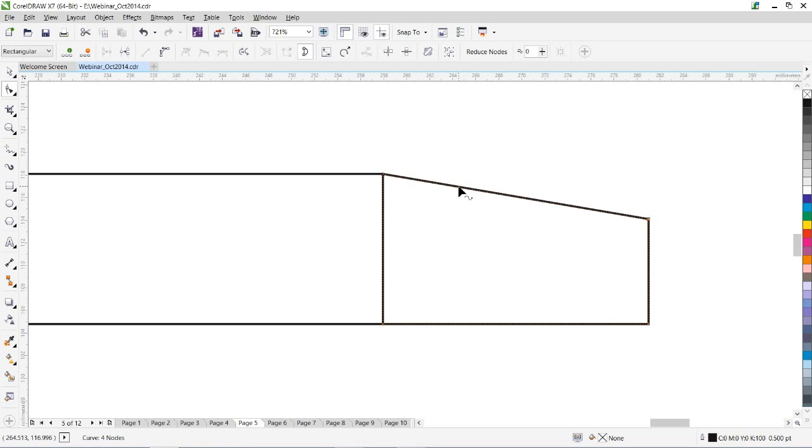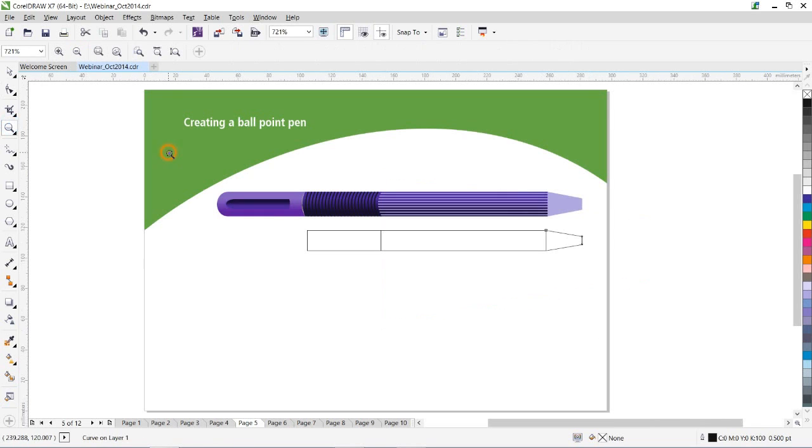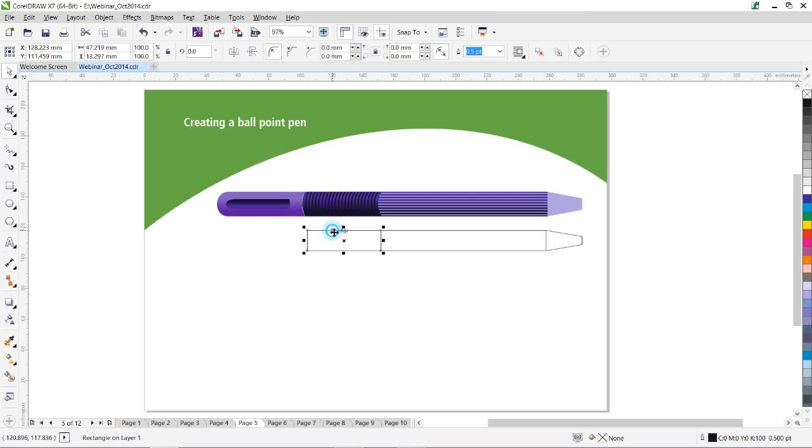It has moved 4 mm now. Same thing here, I select the node, shift click the up arrow and it is shifted by 4 mm. So double the size, double the movement with the Shift key, and half of the nudge set movement with the Control key.